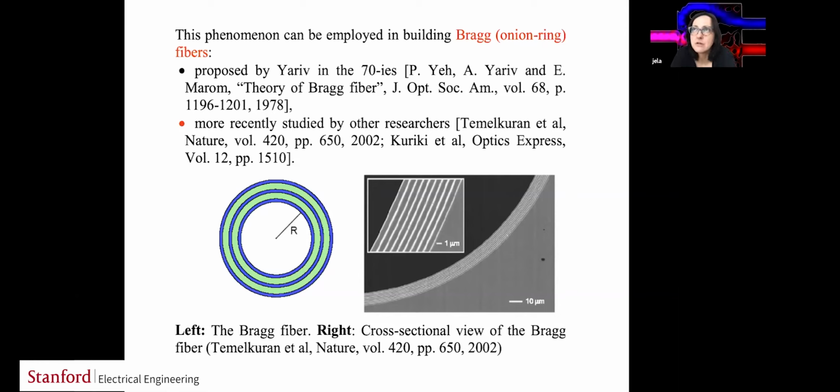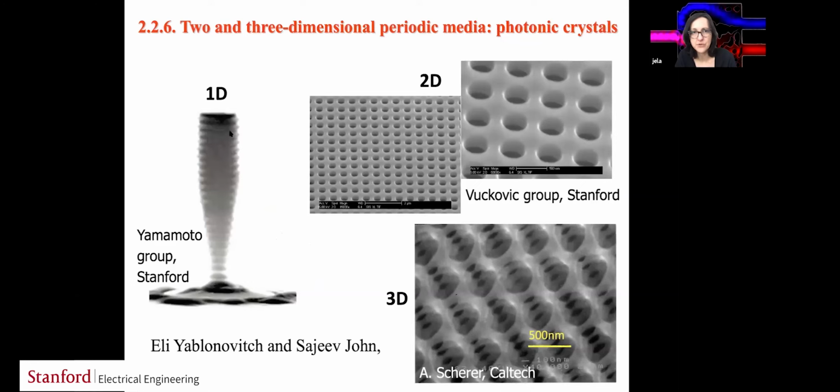It turns out there are methods that people have developed, pretty close to numerical methods, where you can decompose that problem into an infinite Bragg stack, which is the problem that we solved. And that's your one-dimensional master equation. And then you have the other 2 dimensions, which lead to mode confinement. I can actually show it on this picture. Look at this, right? It's your one-dimensional Bragg stack, but confined. And we will be solving this using that method.